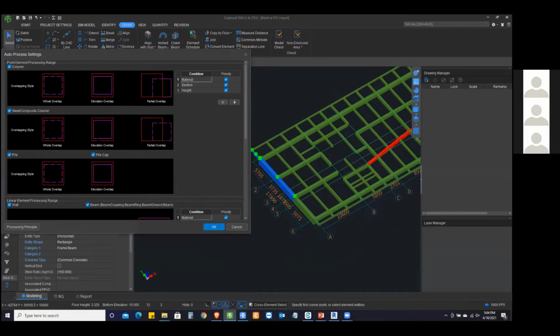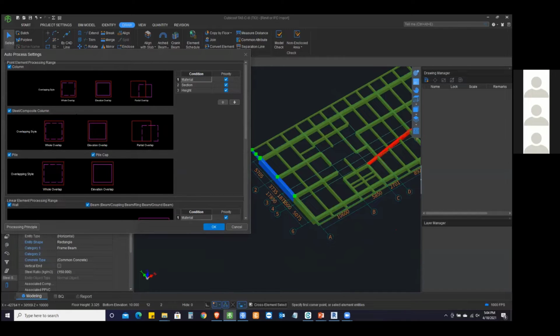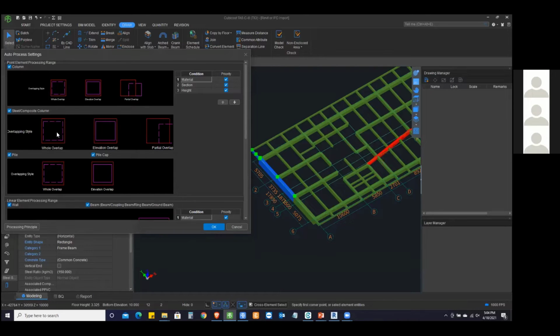The settings show you the software is following the measurement rules which we talked about yesterday. Indian Standard IS 1200 gives us different clauses for how the trimming should happen between different elements, which should oversee which one, which should be below which one level-wise. You get to see that for wall and beam, for column, for steel element, for pile, it's giving different options.